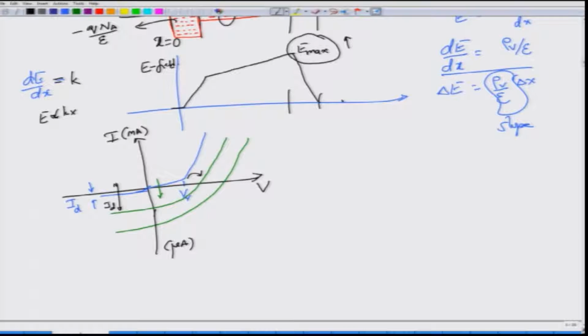One last point about the materials before we move on. We said that if you take a typical semiconductor material, for the absorption of light, you see that there is a drastic cutoff, right, at some cutoff wavelength lambda c. Photons of wavelength lambda greater than lambda c will not be absorbed. This is important, it will not be absorbed. Only those photons with lambda less than lambda c will be absorbed.